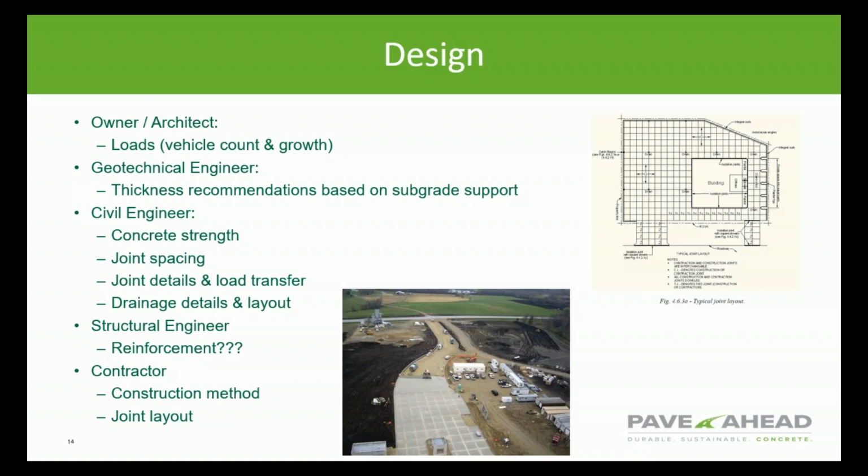The structural engineer, this is a tricky one. The structural engineer will typically design the interior floor slabs, and they make it a structural slab. And many think that since the exterior slab is going to be subjected to the same loads, the same design should be used, and that's really not true. What that's going to lead to is reinforcing the exterior pavement more so than it needs to be.